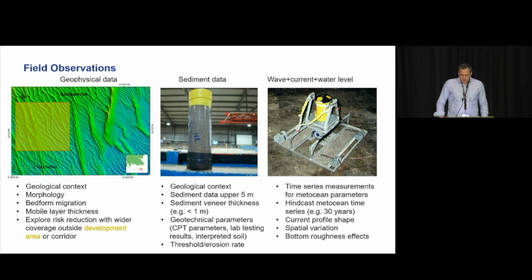I've got a point there about the geotechnical parameters and the fact that CPT can be useful. I know this is a question from Richard, really a challenge from Richard. So CPT is often considered to be a little bit debatable in the top metre or so from a geotechnical perspective, but CPTs do still record something, and that may be related to the sediment erosion properties or the sediment properties generally. So that's something that he's keen to continue to work on going forwards, about the value you can extract from that from the perspective of sediment transport. So samples are really, really crucial.